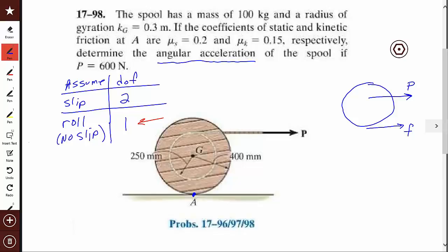So it's friction. All I know is that because there is no slip, the friction is less than or equal to mu Sn. I do not know that it is equal to mu Sn. I only know that it's less than or equal to. So I really don't know the direction. So I just put it in there. This is a normal force. It's a pressure basically from the floor. And then I also have a weight that's acting down through the center. So those are the forces.